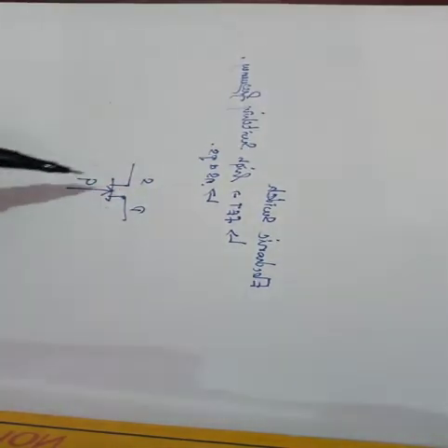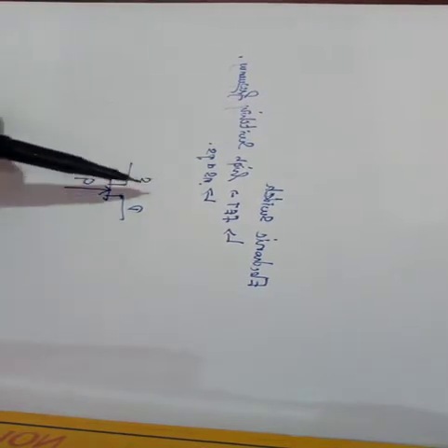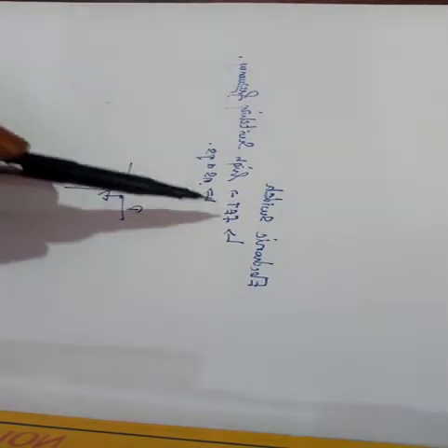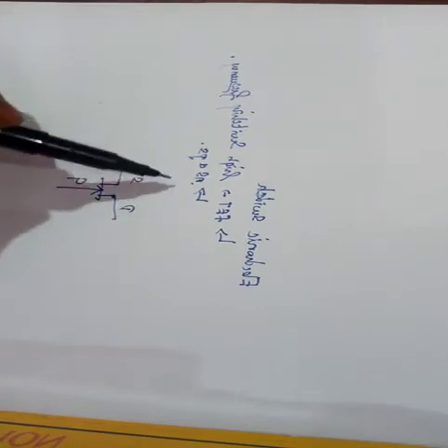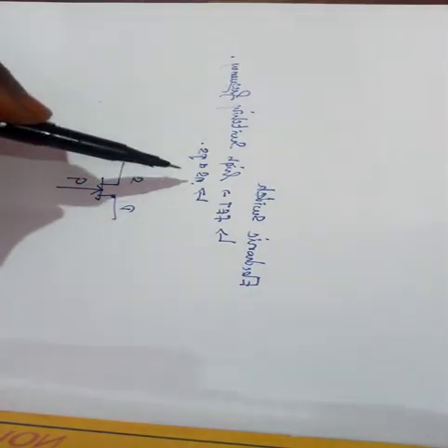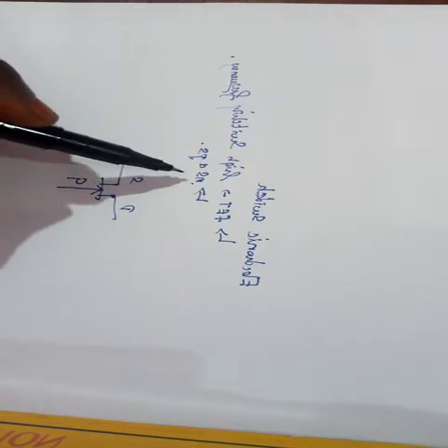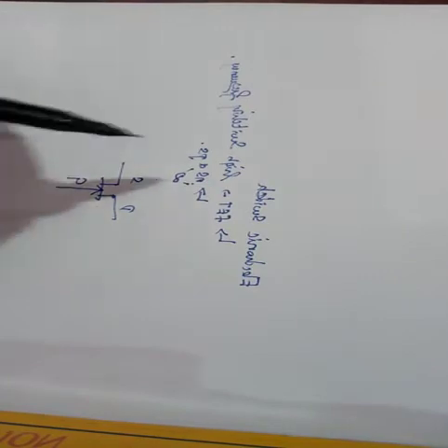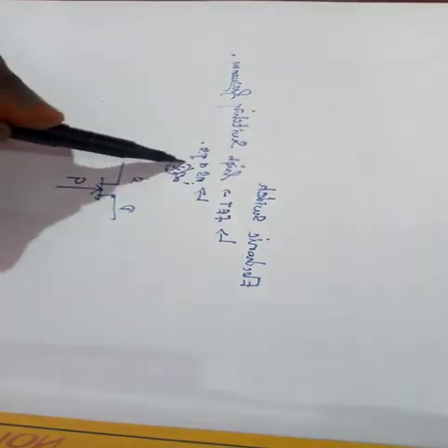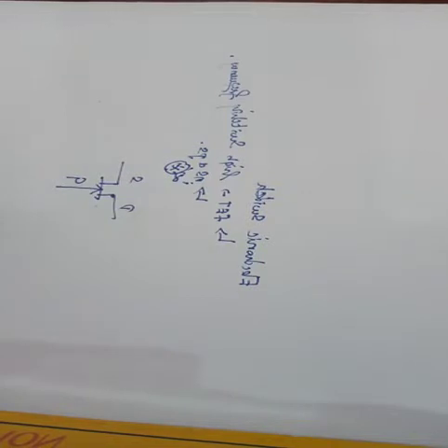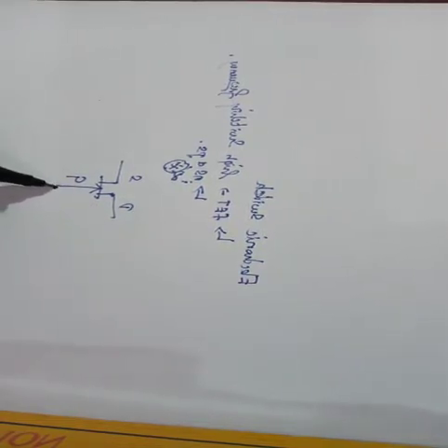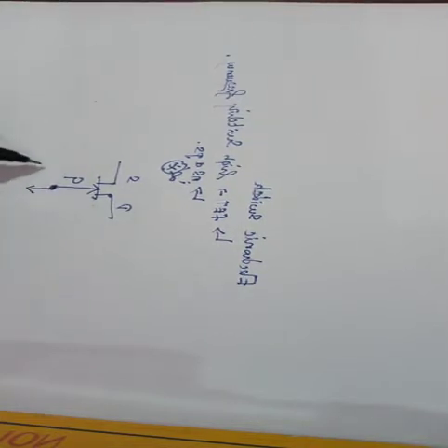One more thing I need to say is, for FET kind of switches, the input impedance will be in the ranges of infinity during the off state. It is very important. During the off state, the impedance offered by the switch will be infinite. So it is also a very advantageous aspect. I can use another kind of signal here in order to turn this on and off.